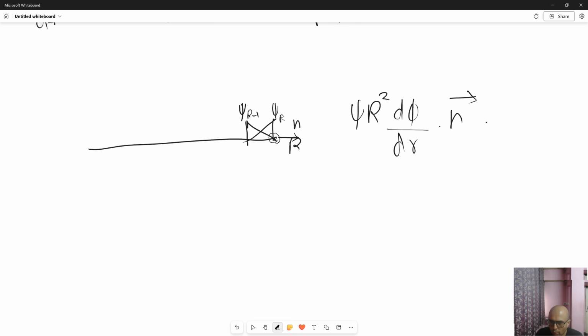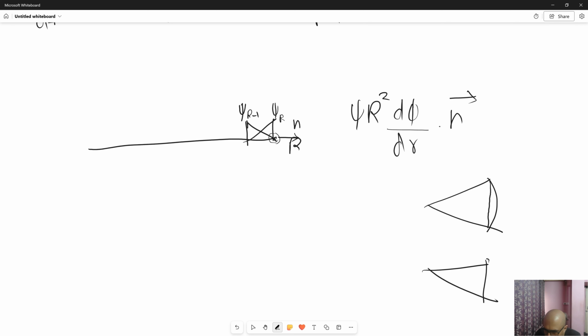So here this is just a point integral, but if this was a 2D case, and let's say I was using a triangle to represent this 2D case, then this would rather be a representation like this. Then I would have two nodes here, and I would have this boundary, and in that case the boundary term would be something like test function into flux dotted with the unit normal in the outward direction.